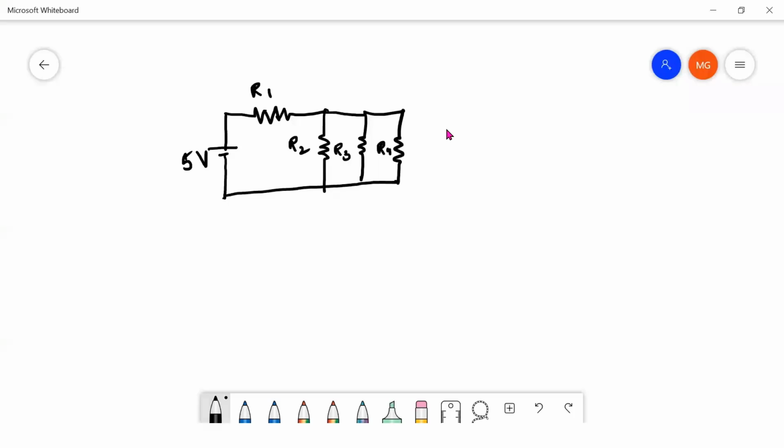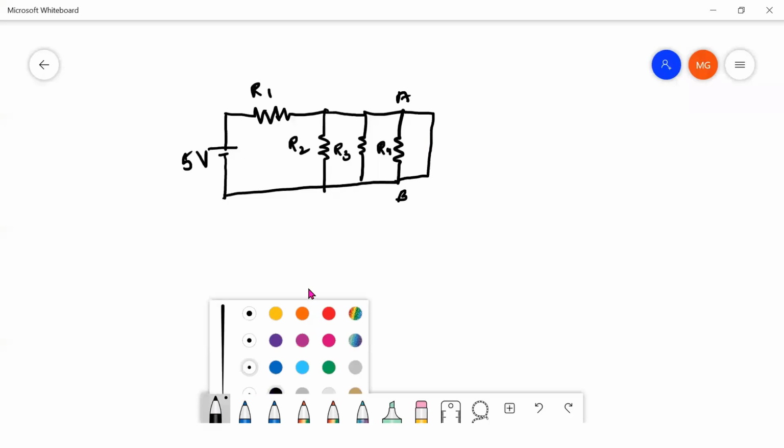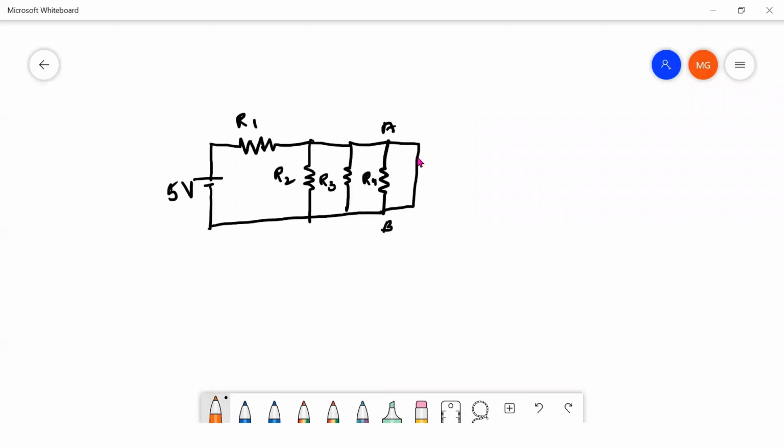For that circuit, simply one wire is added between the nodes A and B. Solve for this network. If this is a question, then how to solve it? Because of this short, R4 can be neglected. As a result, whether it is present in the network or not, it doesn't matter. Okay, R4 is neglected. Then what about R3? Again, it is shorted, so even R3 can also be neglected, whether it is present in the network or not, it doesn't matter.